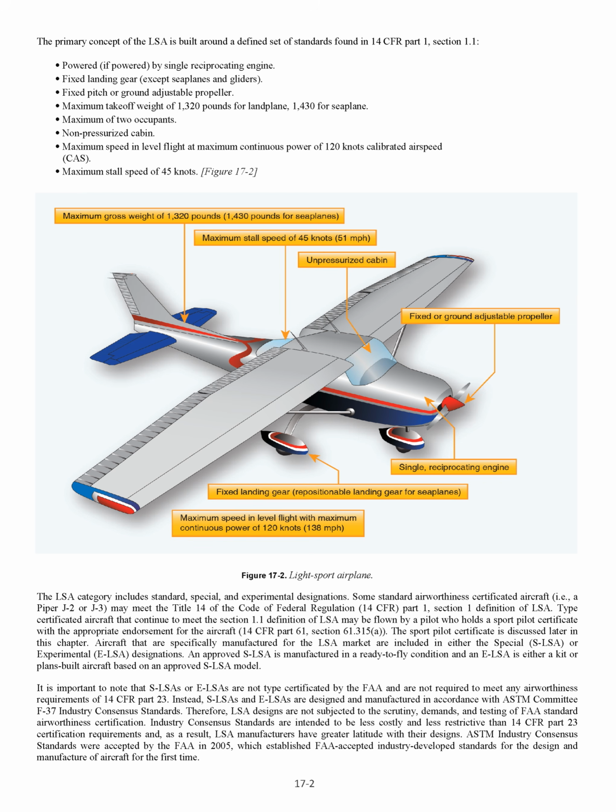Instead, SLSAs and ELSAs are designed and manufactured in accordance with ASTM Committee F37 industry consensus standards. Therefore, LSA designs are not subjected to the scrutiny, demands, and testing of FAA standard airworthiness certification. Industry consensus standards are intended to be less costly and less restrictive than 14 CFR Part 23 certification requirements and, as a result, LSA manufacturers have greater latitude with their designs. ASTM industry consensus standards were accepted by the FAA in 2005, which established FAA-accepted industry-developed standards for the design and manufacture of aircraft for the first time.